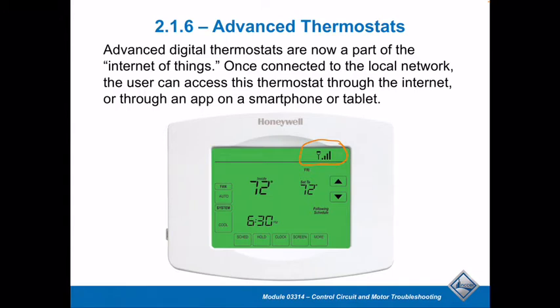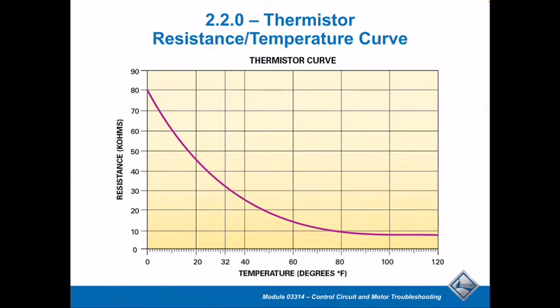This is typical of what would be going on with these line voltage thermostats. The whole reason for that was primarily the current flow going through the contacts. There was a certain amount of heat that would build up as it carried the load. You typically don't see that happen with low voltage thermostats, but you can almost equate it to an anticipator to some extent. Interesting. So let's get into the next part of this.